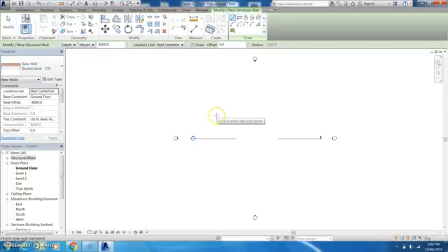And I'm going to come down to our drawing here. Now, a few things. We've got this other line that comes up here with some more settings. First of all, our location of the line. We can draw from the wall center line, or things like the face finish interior or the finish face exterior. So it gives us a number of options there.